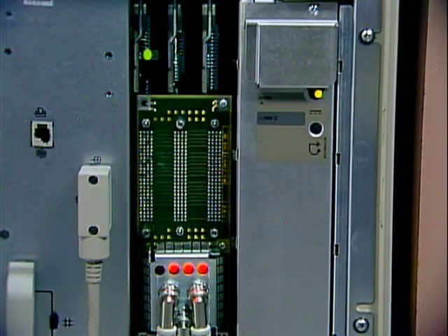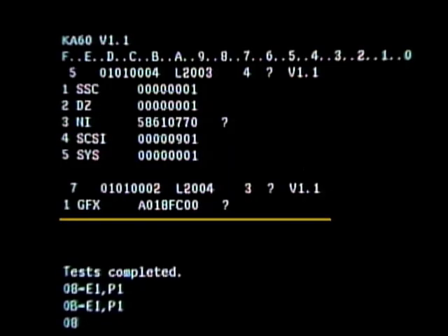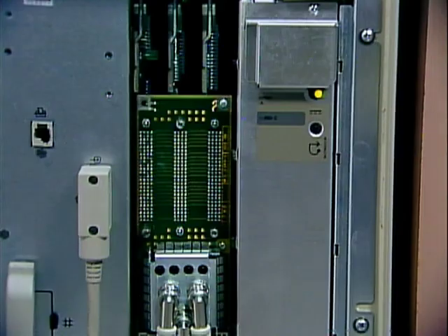While the diagnostic code is being executed, the green LED and one or more red LEDs will be lit. Upon successful completion of the PST, the green LED will remain lit and all red LEDs on the graphics front plane will be off. When the graphic test detects an error, the green indicator will be turned off. To interpret the error, first check LED number 3. This is the rightmost LED. If it is lit, the diagnostic couldn't determine the exact cause of the problem.